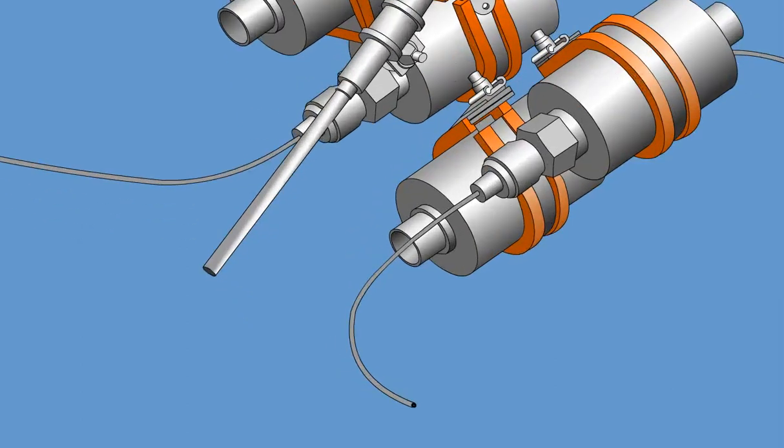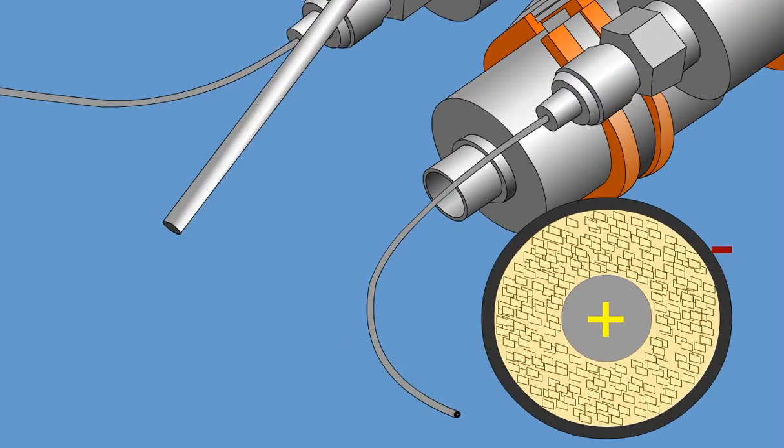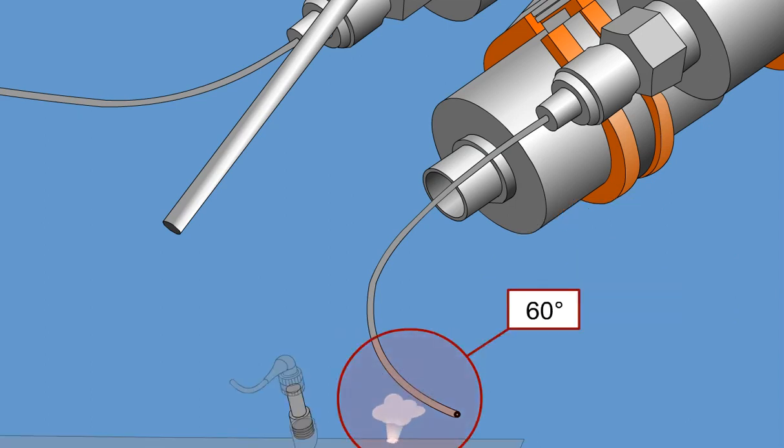The fin wall sensor loops include outer and inner conductive materials which are independent electrical circuits. The area between the outer and inner walls of the loops is filled with salt. If the temperature of the loops rises above 125 degrees Celsius, the circuits develop a short.